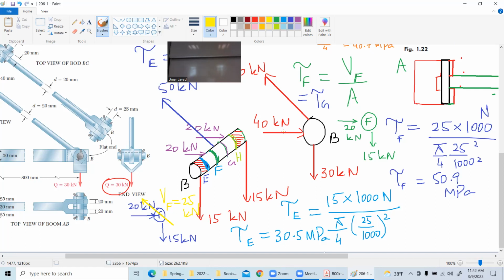The big problem is that this hole has absolutely nothing to do with this. So that's why I did 40 minus 25, multiplied by 20. The 20 for me is the thickness, because the top view tells me that in the z dimension, the height, it is thickness or depth. That's how the force flows through that little chunk.